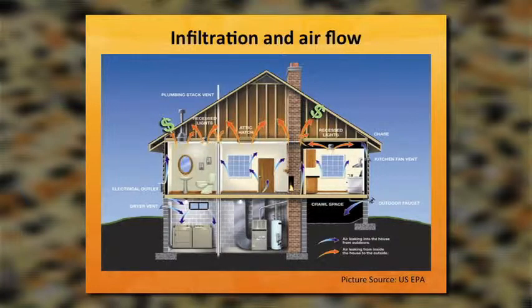So through vents, our bath vents, recessed can lights, plumbing stacks, so the holes at the top of interior walls where it allows air to get through and out into the attic. Attic access hatch, this is one of the really serious ones, as well as whenever we have a flue pipe or a chimney that goes through the ceiling line, we're going to find some exfiltration there.